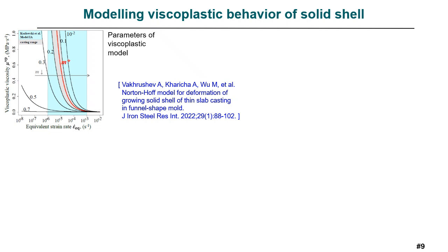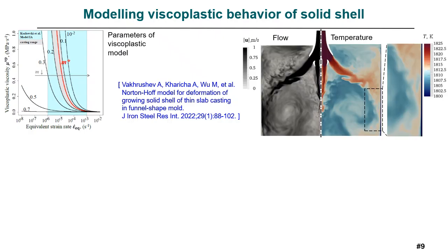Conventionally, the motion of the solidified shell is described by a static distribution of the casting velocities. However, such an approach is insufficient if we would like to predict more complex phenomena such as crack formation, depressions, and other mechanical defects.